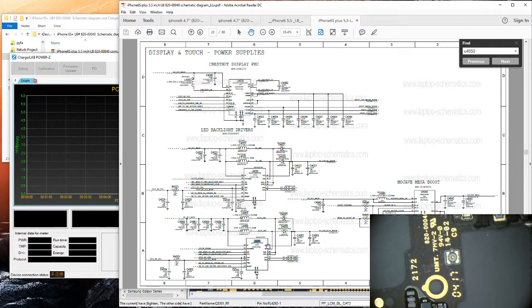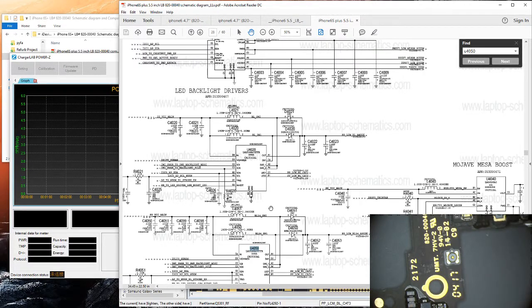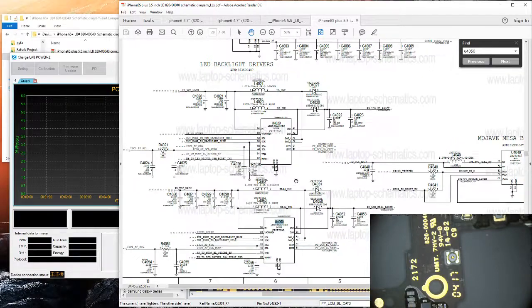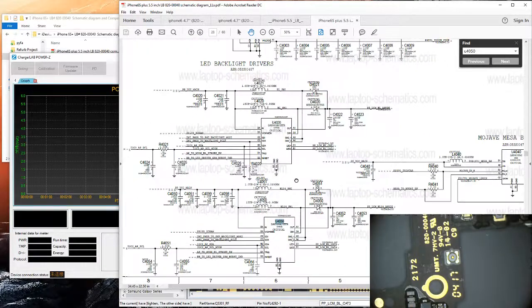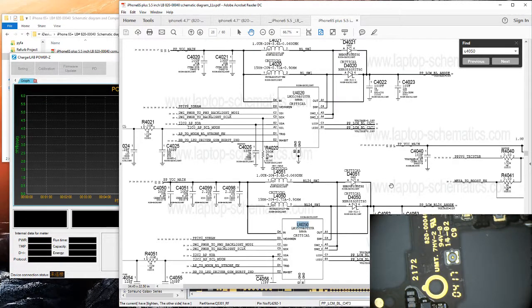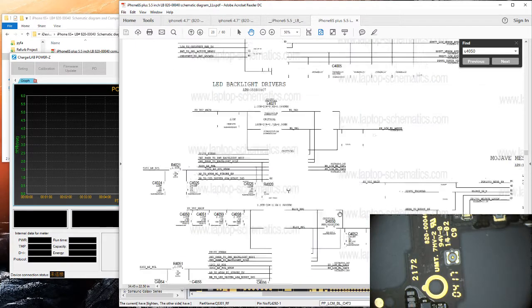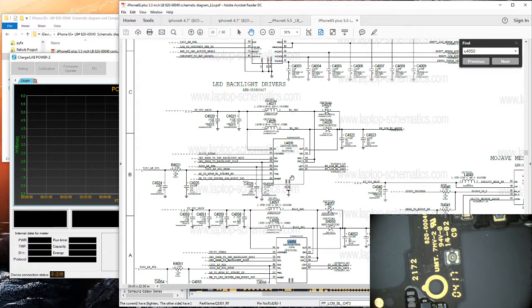Okay, this ought to look familiar. Compare this to the backlight circuit we were just looking at. God, this PDF is slow. The only major difference is that instead of having one coil and one diode, you just have two of them in parallel on each circuit. So it's basically 4 times the circuit. You got 2 drivers, 2 coils per driver, 2 diodes per driver, and a handful of caps and stuff that go on the VCC main side and then back out the anode side.